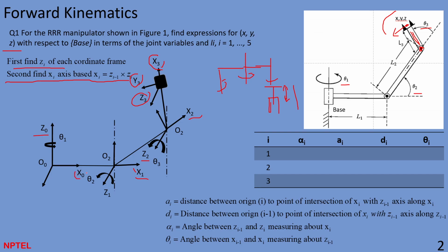For the base frame, you can take it arbitrarily, but if you know x1, x2, x3, it's good practice that you take x naught along the x1 axis.